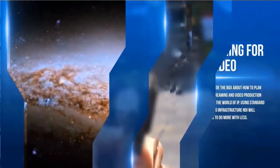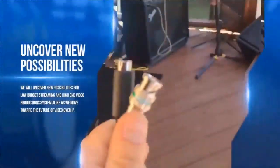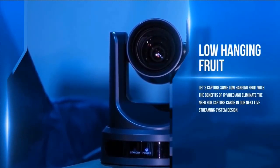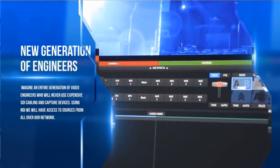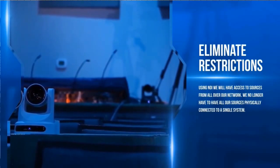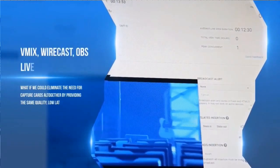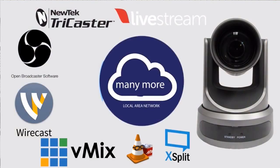Imagine an entire generation of video engineers who will never use expensive SDI cabling and capture devices. Using NDI, we'll have access to sources from anywhere on our network. We will no longer be restricted to sources directly connected to a single system. Capture cards are used for low-latency video conversion from traditional HDMI or SDI video to USB or PCIe, where we can use them with production software, such as vMix, Wirecast, Livestream, and more. What if we could eliminate the need for capture cards altogether by providing the same quality, low-latency video directly to Wirecast, vMix, Livestream, OBS, or XSplit over the Ethernet connection we're already using?